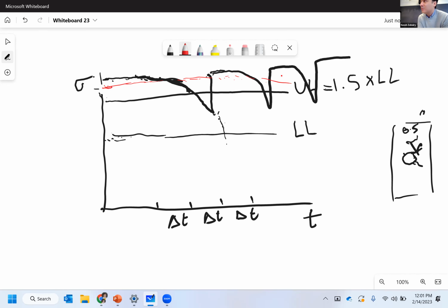But what happens is that once in a while you have impact on composite, like a small bird strike impact. I mentioned like there is a maintenance crew, they're walking around, someone is walking over the wing and they drop their toolbox on the wing. It's an impact. It has effect. So what will happen is that the moment you have impact, the strength of the material drops, sometimes significantly. And it might drop below the ultimate load.